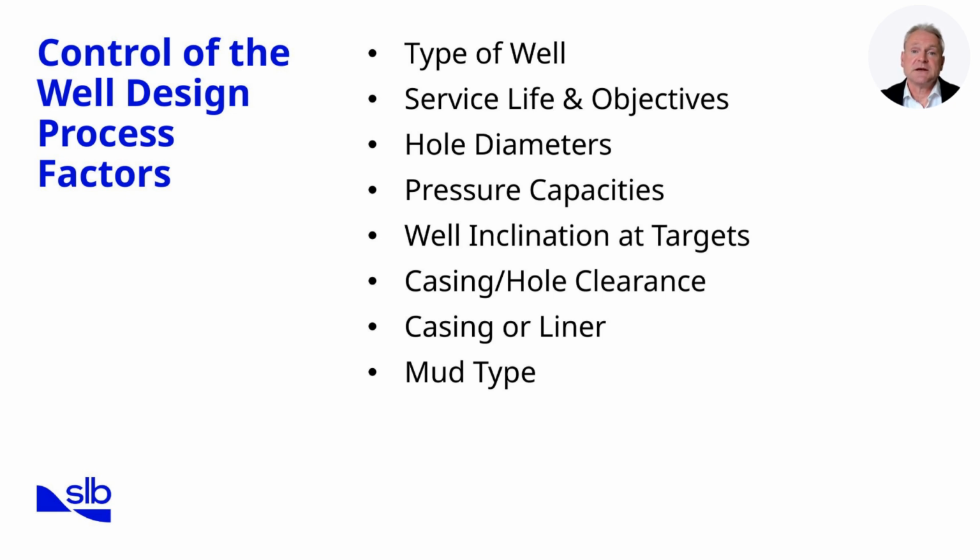Next, we look at service life and objectives. Wells designed for long-term production may need different casing materials and safety margins compared to short-term appraisal or injector wells. Hole diameters also fall within our control. Choosing the correct size impacts casing strings, completion hardware, and ultimately production capacity.